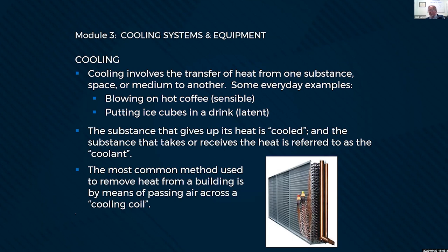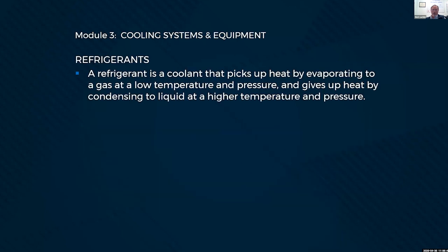So a coolant can be a liquid that never changes state, that just changes temperature, or it can be a refrigerant. We'll get into that in a little bit. How about right now? A refrigerant is a coolant that picks up heat by evaporating to a gas at low temperature and pressure, and gives its heat back up when it condenses to a liquid. So you've got change of state, you've got latent heat transfer going on, as opposed to just sensible, like in a liquid cooling coil.